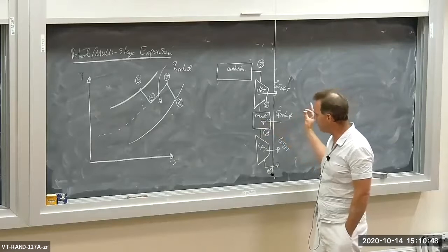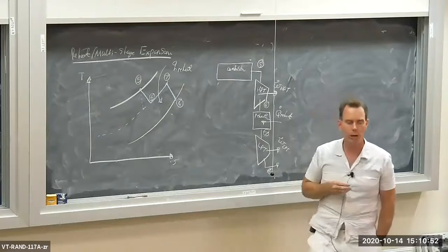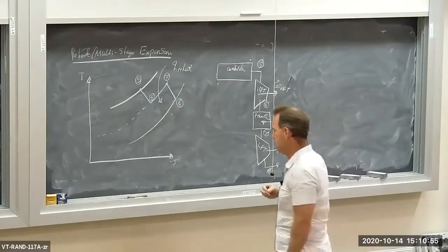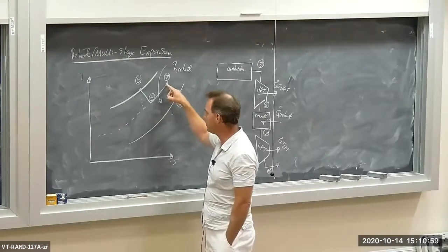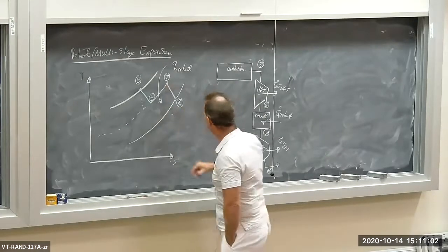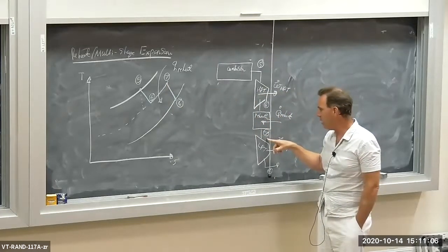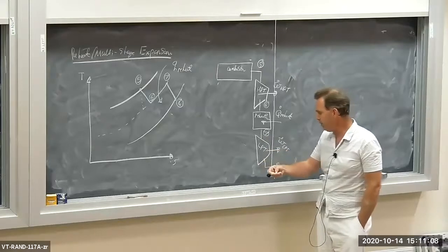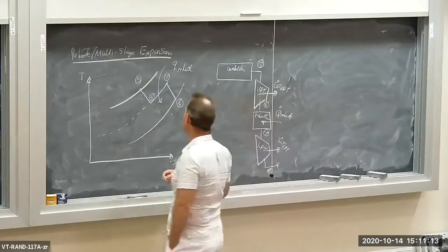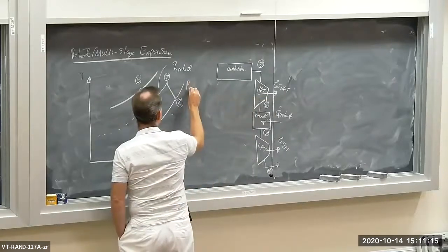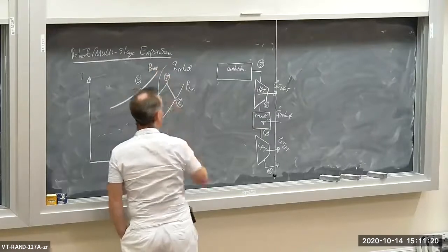We inject more fuel, and we burn more fuel in a combustion chamber called a reheater. So we add more fuel, temperature goes up, entropy goes up because we're releasing heat, and then we expand the now hotter air through a low pressure turbine until we get down to the minimum pressure. So we got P min here, and we got P max here, and we have some intermediate pressure in between.